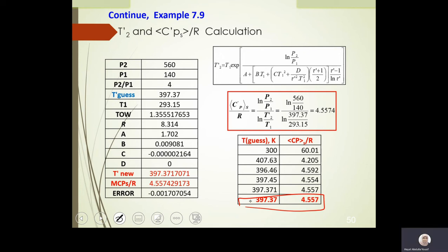Just a quick illustration, a quick example on the pump. Here is the pump, and at the inlet I have a temperature. The fluid gets in at 45 degrees C and the pressure is 10 kilopascal. Normally with the pump, the most important factor we need to know is the outlet pressure, because the pump is pumping, so the main change is the pressure. They already give me that the pressure is 8,600 kilopascal at the outlet, so from 10 kilopascal to 8,600 kilopascal.